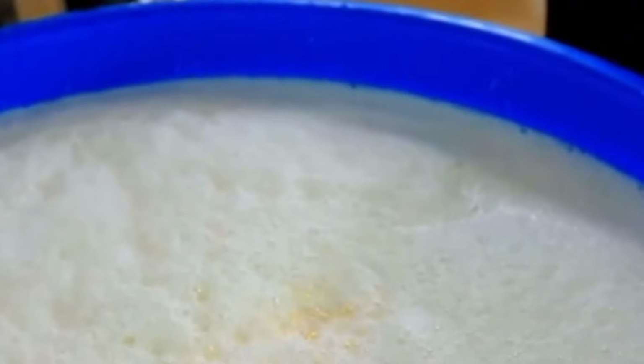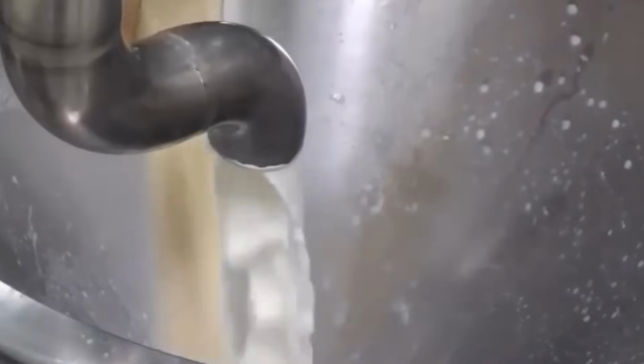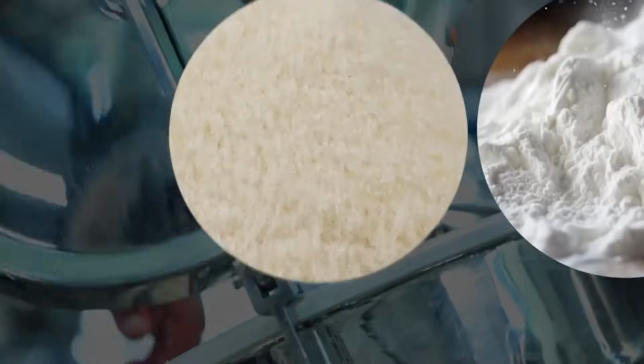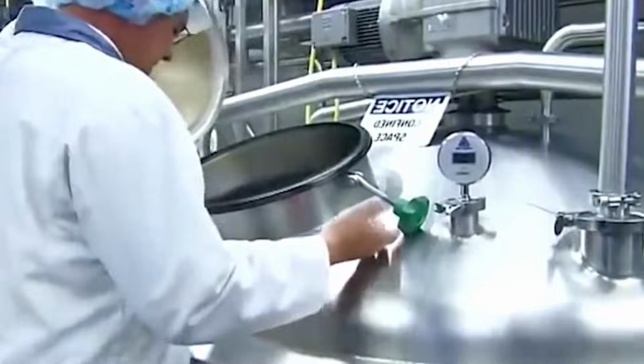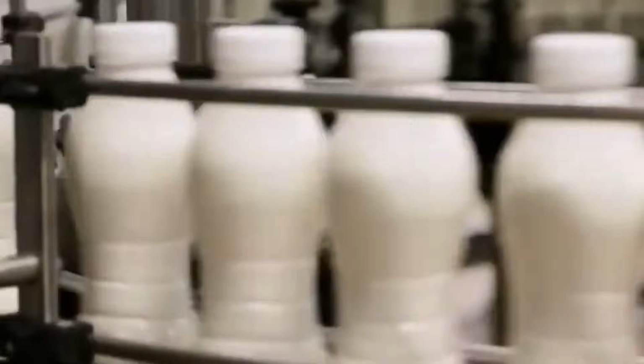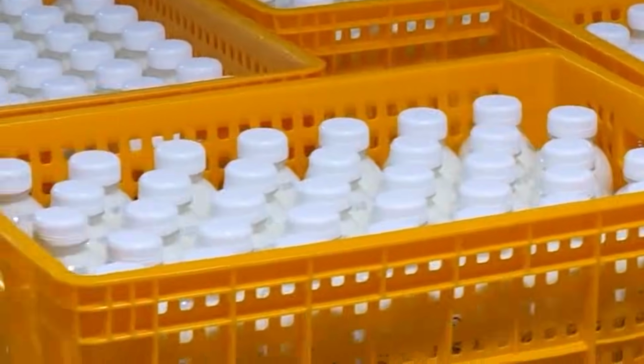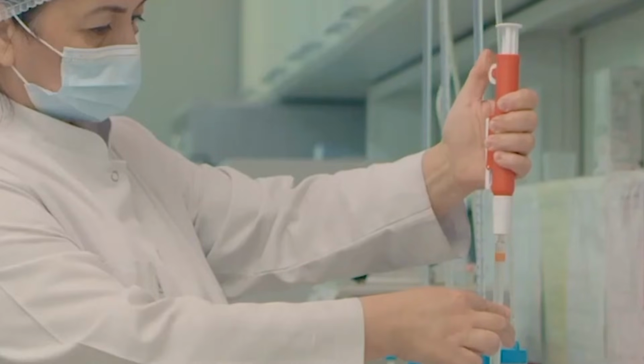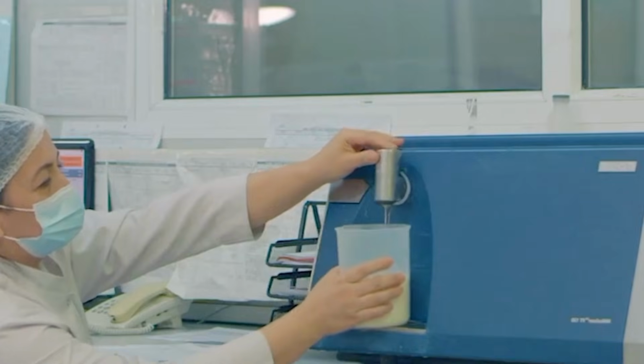Bulk dairy ingredients, such as skimmed milk, whole milk, and cream, are stored in stainless steel, temperature-controlled silos or tanks held between 1 and 4 degrees Celsius. These tanks are fitted with slow-speed agitators to prevent fat separation and sedimentation. From the tanks, ingredients are drawn through dedicated pipelines with volumetric flow meters that measure and regulate dosing rates with tolerances within ±0.2%.